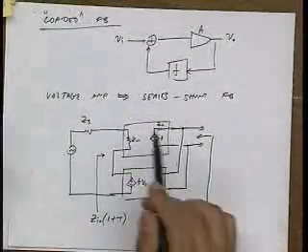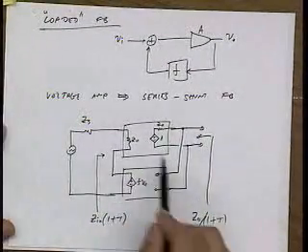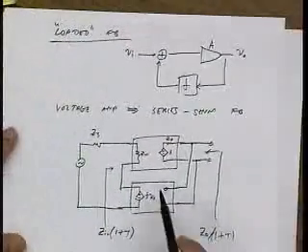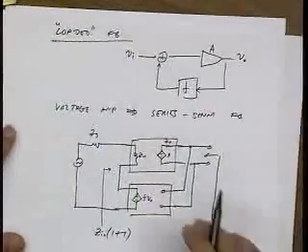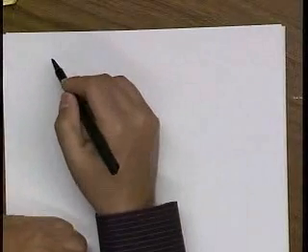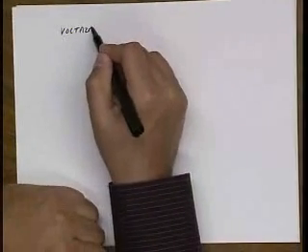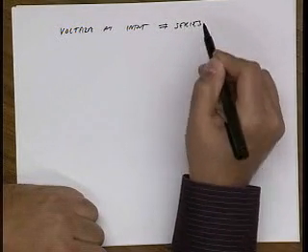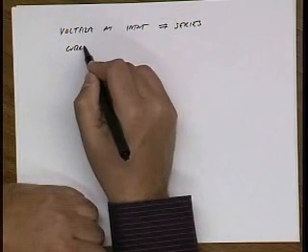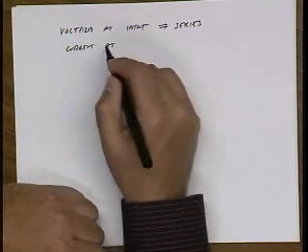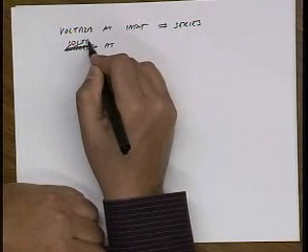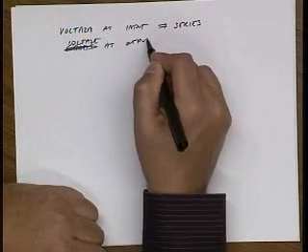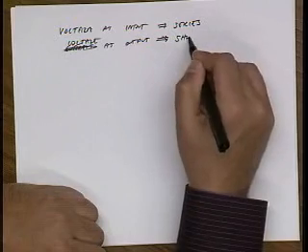Let's see how we could do this, right? Now let's go from a real amplifier and try to derive something that looks like this. And in the process, we'll see all the approximations that are necessary to make an ideal voltage feedback system. All right, so let me emphasize that I have voltage at the input, in other words, a series connection, and current at the output. Actually, I'm sorry, voltage at the output. So I have a shunt connection.